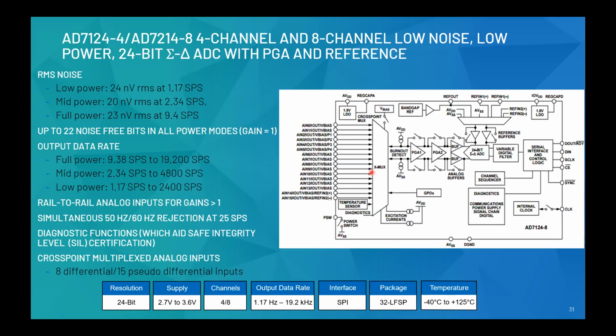So if you look at an application, you could just connect a sensor over here, and you should be done with your complete measurement. It does offer a lot of diagnostics, right, which aid SIL level applications or functional safety applications, and this is very much appreciated by a lot of customers, as their overall journey of achieving SIL certification is much simplified by the amount of diagnostics that we have in the part.